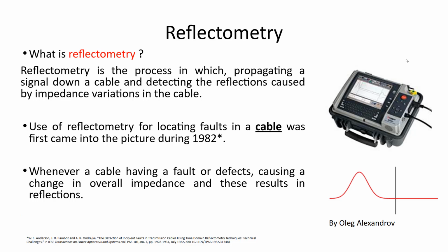The study of the reflections tells us what happened: whether there is a short circuit fault, and if there is, at what location, and whether there is some problem in the insulation. So this is the basic philosophy of the method.